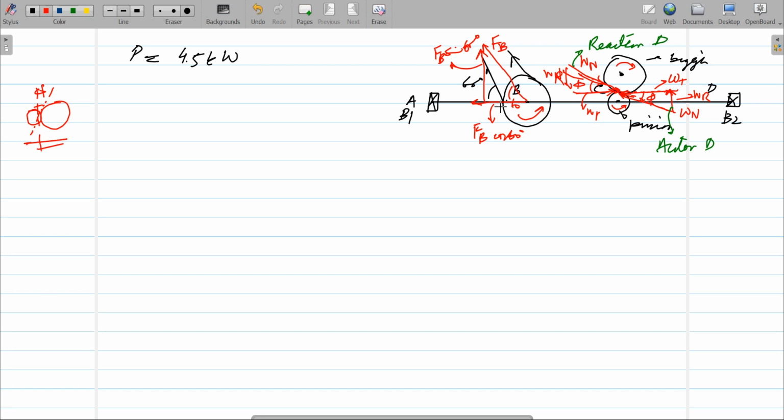Again, in case of a pulley, you have to see in which direction the pulley could be, like this. You have a pulley which could be like this. So we have to use this, and then we can draw cos and sine components. So it could be at any angle. It could be a sprocket as well. So in case of sprockets and pulleys, the belt-pulley system, the forces are defined on the same principle, that is, in which direction the belt is, at which angle with respect to horizontal or vertical the belt is moving, you can draw the angle.